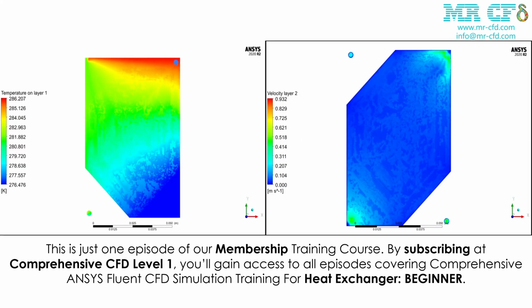After the simulation, the results including temperature and velocity contours are obtained for each of 4 layers. Layers are planes parallel to the XY plane which are assigned 1 to 4 as their Z increases. Layers 1 and 3 are regions where the cold flow is heated up, and layers 2 and 4 are regions where hot flow is cooled down.